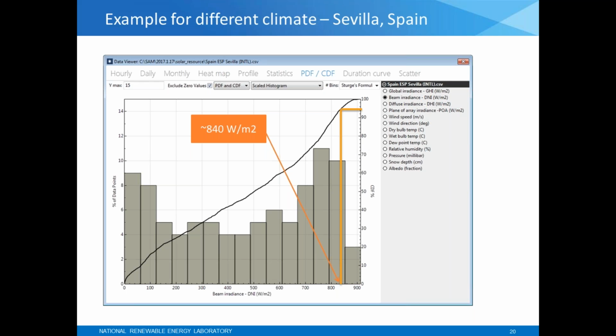It's something that when you're looking through your case, you're going to want to optimize. It may be that you go and buy an HTF pump that is rated to just the design power of the system. And so anytime you go above your design point DNI, you're going to have to start dumping energy from the system. So in that case, maybe you'd want to be closer to 100%.